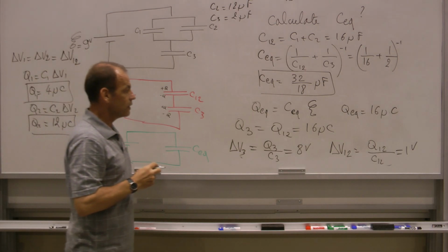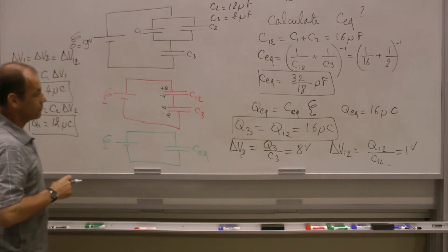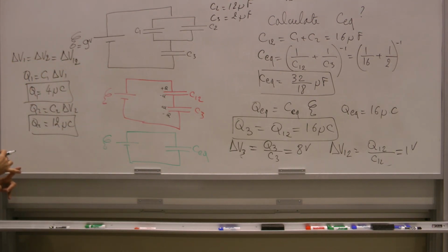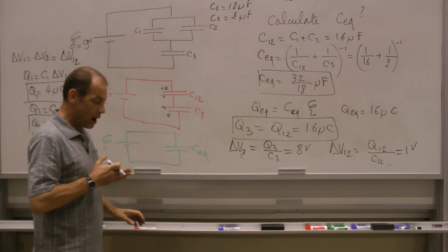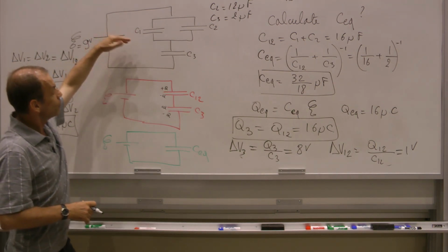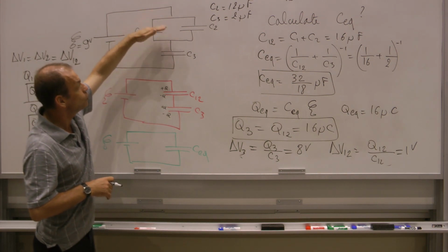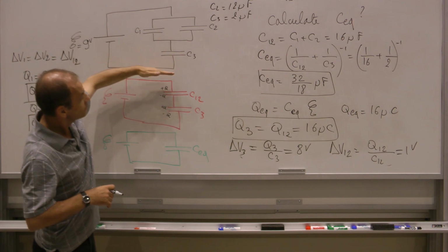We have now all the information corresponding to these capacitors. We have the voltage across them, we have the charge held by them, we've solved our problem. So classic problem. We start from the beginning, from what is given to us, the circuit. If we have any capacitors that can be rearranged into equivalent capacitors, we do so. And we proceed step by step.